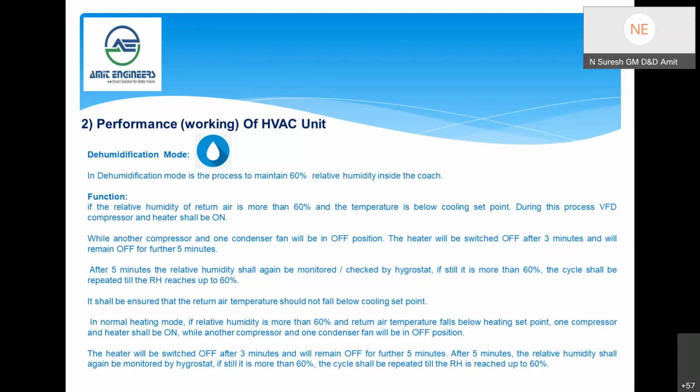If the humidity is very high in some areas, we have to run the refrigeration system for more time compared to the lower RH condition. In that case, the temperature will come down. To maintain the desired or human comfort temperature, the heater will go on and off.